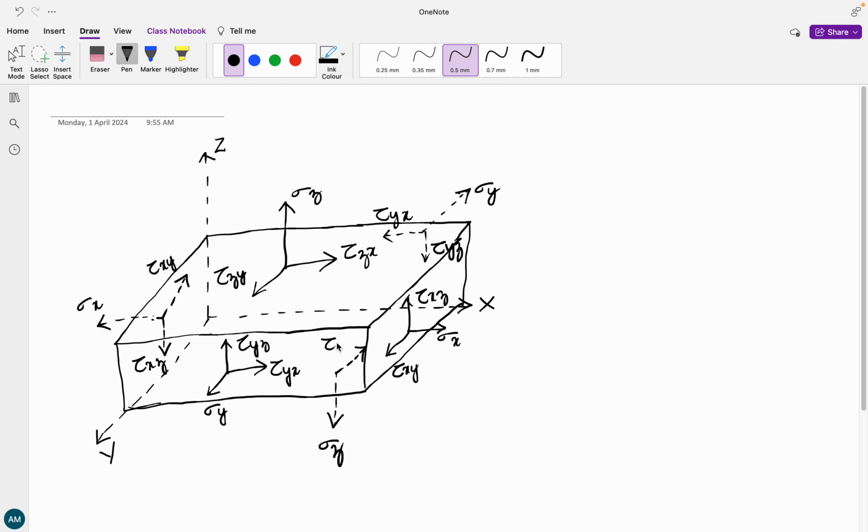So now along the negative axis I am going to write tau zy. Along positive x it was tau zx. Now along negative it's going to be tau zx. Okay. So here we have represented all the forces, the 9 components of your stress at a point, that is your stress tensor, in a parallelepiped.